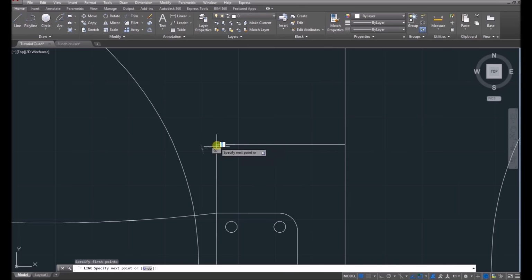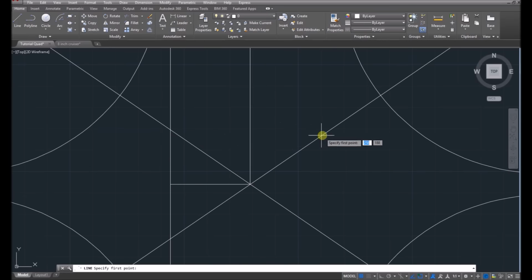So there you go. Let's say we're going to have our Naze right in the middle. The hole spacing for a Naze32 is 30.5 millimeters each way. So that means what you've got to do is get your line tool and go up 15.25, then you go across 15.25, and that's where our hole will sit. 1.6 millimeter hole.